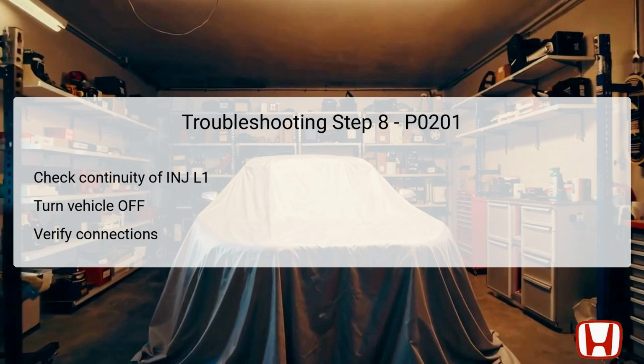If both lines check out well, the next course of action is to refer to any authorized service information related to DTCs or symptoms being dealt with in this troubleshooting session. You may also consider replacing the PCM with a known good unit to rule out its function.